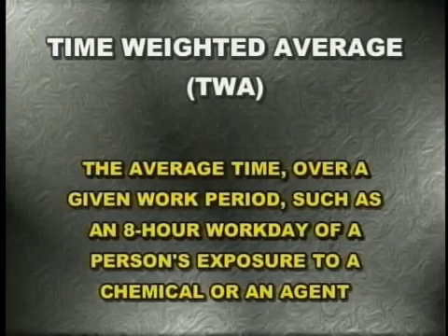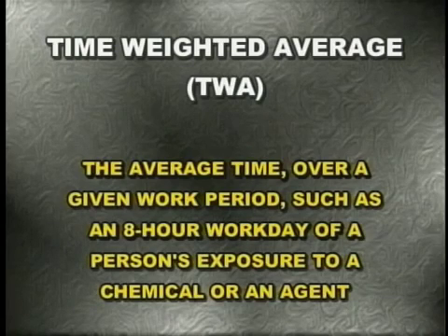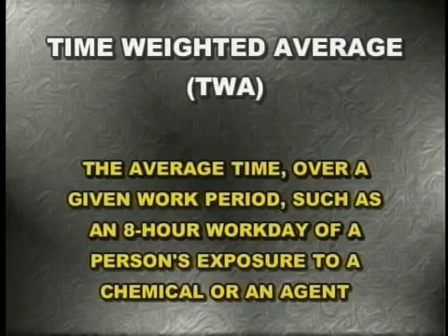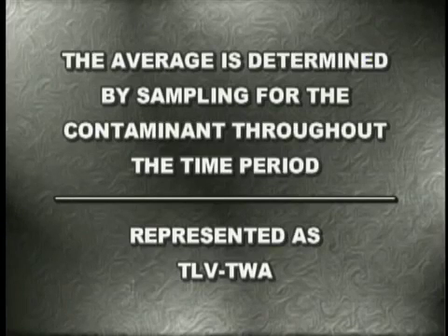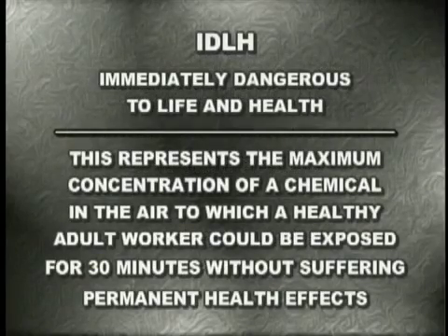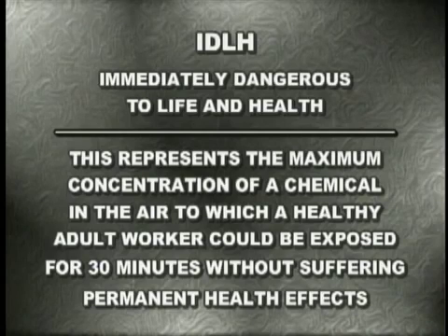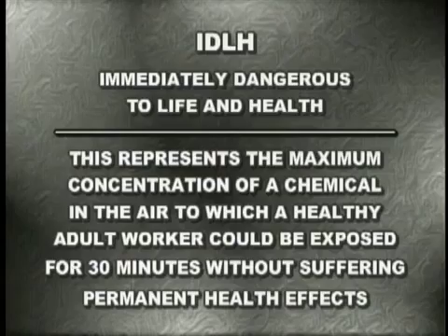Time-weighted average, TWA. The average time over a given work period, such as an 8-hour workday, of a person's exposure to a chemical or an agent. The average is determined by sampling for the contaminant throughout the time period, represented as TLV-TWA. IDLH, immediately dangerous to life and health, which represents the maximum concentration of a chemical in the air to which a healthy adult worker could be exposed for 30 minutes without suffering permanent or escape-impairing health effects.